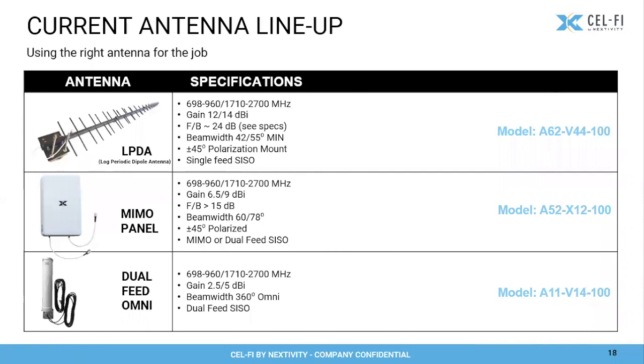This would be the least apt to clean up any kind of signal to noise, but if your SINR is really, really good for all the operators you want to serve, then there's no reason why you can't use this antenna. A good example would be closer to the street where there's just too much interference high up in the building and you can't get decent channels for your operators. Then the Omni down closer to the street level could easily be your solution.